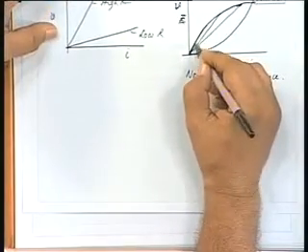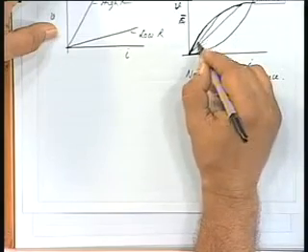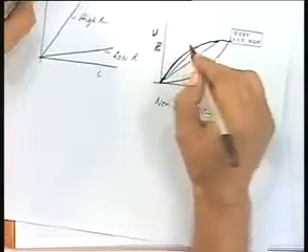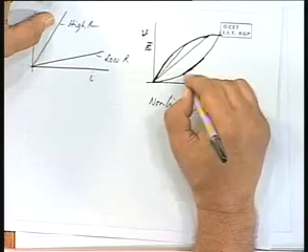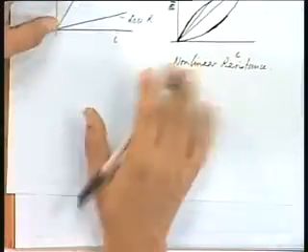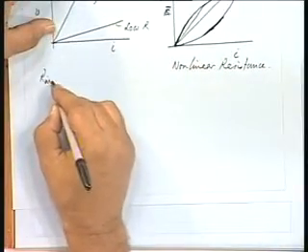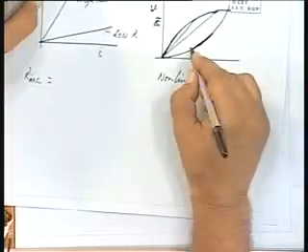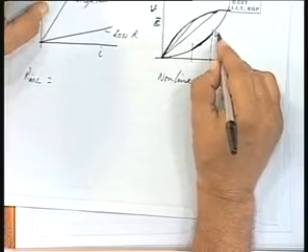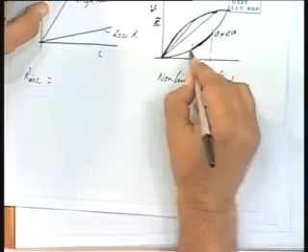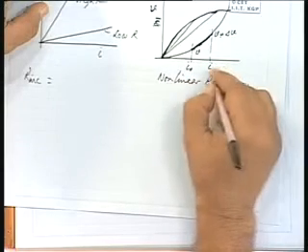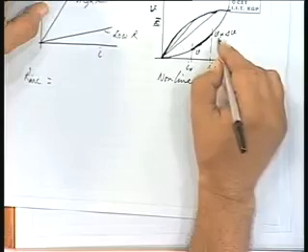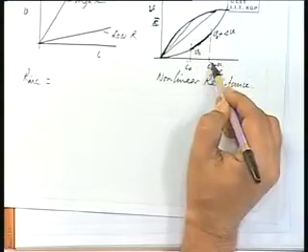So we approximate them to be linear for small values of current, or we linearize around an operating point. Say if this is an operating point, so around this point the slope is taken as the resistance, or we define it as incremental resistance. Suppose this is V and this is I, this is I naught plus delta I, this is V naught and I naught, V naught plus delta V, I naught plus delta I.